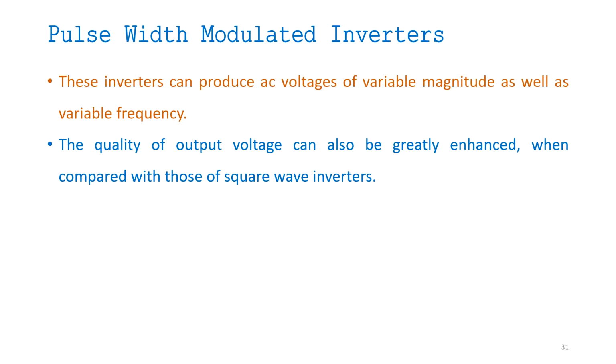Usually our devices are designed for sinusoidal voltages, and if we see the output from the inverter, single phase or three phase, it looks like square waves, which have a lot of harmonics. When you take the Fourier series of these, you have lots of harmonics which will reduce the performance of your device.